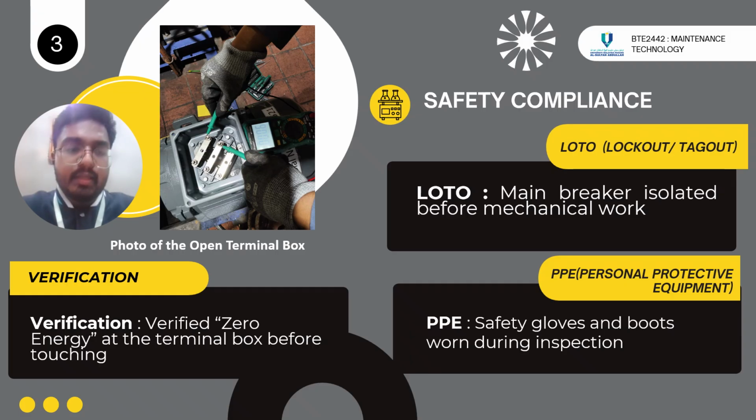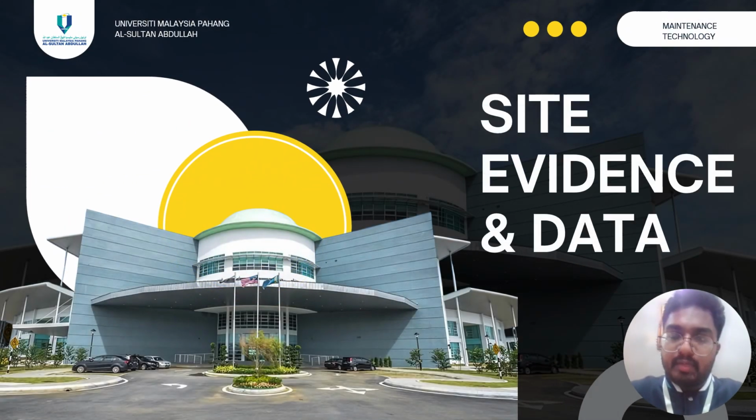We have to verify zero energy at the terminal box before touching it. So there's no electrical energy, so that we don't get shocked by any electrical shock. We must verify that absolutely no electrical flow is going there. And let's see the site evidence and data.